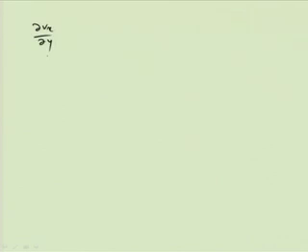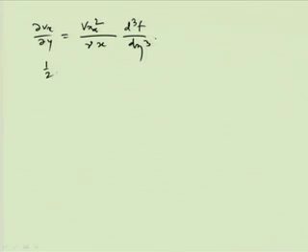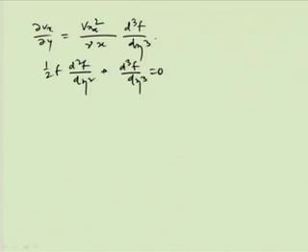We have to put these values into the momentum balance equation. So, this is equal to Vx infinity square by nu into x into d cube f by d eta cube. So, by doing all this, when we put all the values, we finally get half of f d2f by d eta square plus d cube f by d eta cube equals 0.